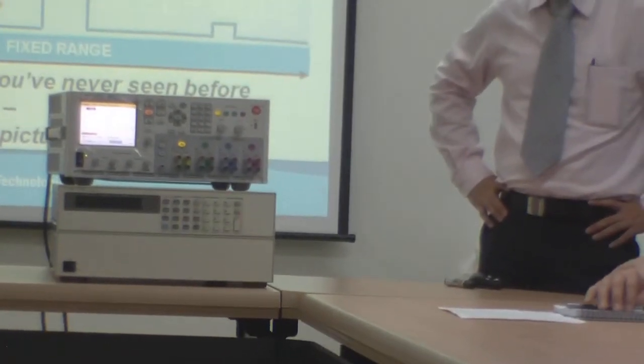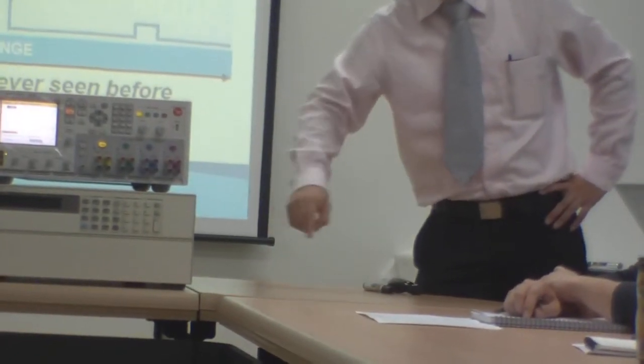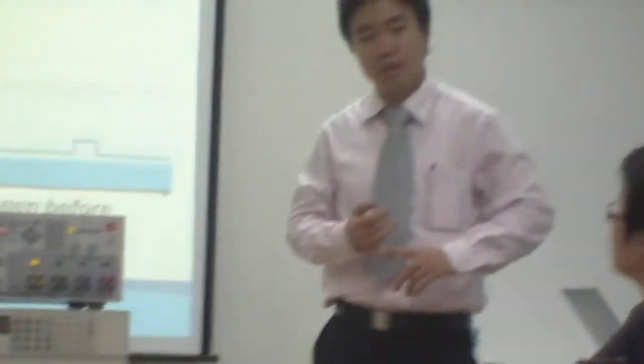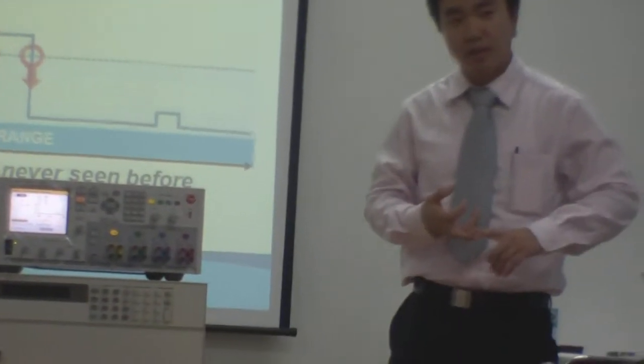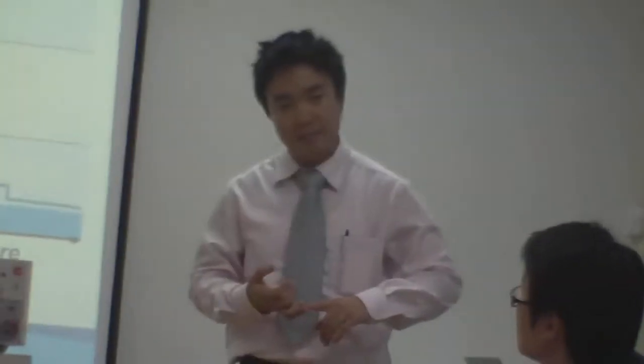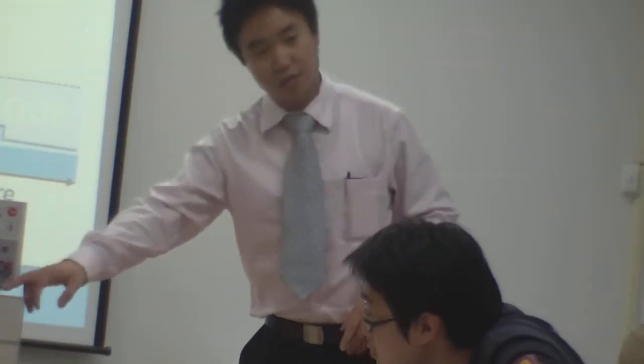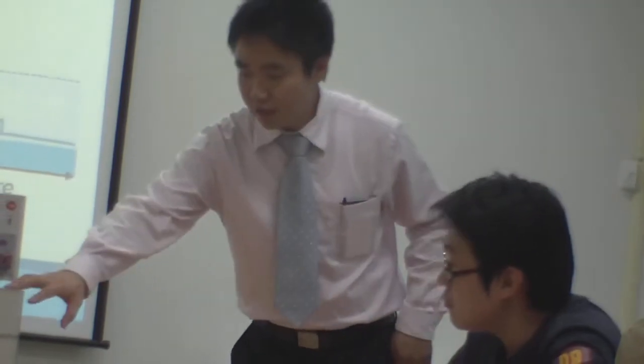I want to control the resistance. The resistance? Okay. You want to control the resistance of the ELO. Okay. So yeah, there's constant current, constant voltage, and also constant resistance mode. Most people use constant current to regulate because constant resistance is in some ways just constant current. If you know the resistance, then you know the current that you want to sink, and you can program it directly.